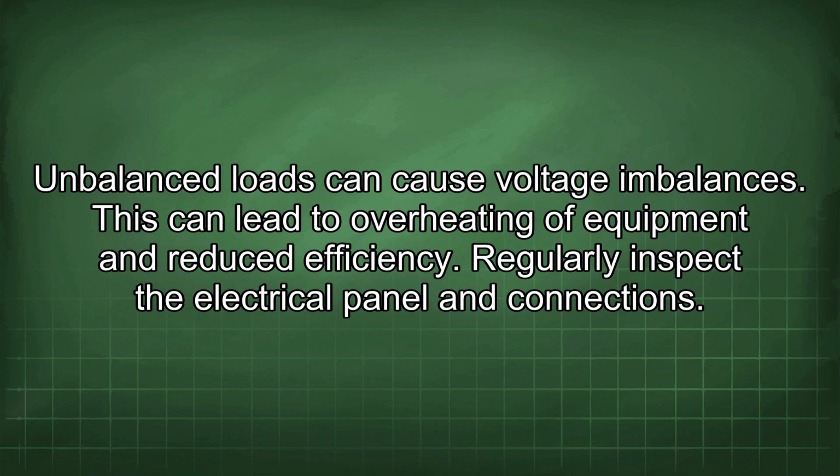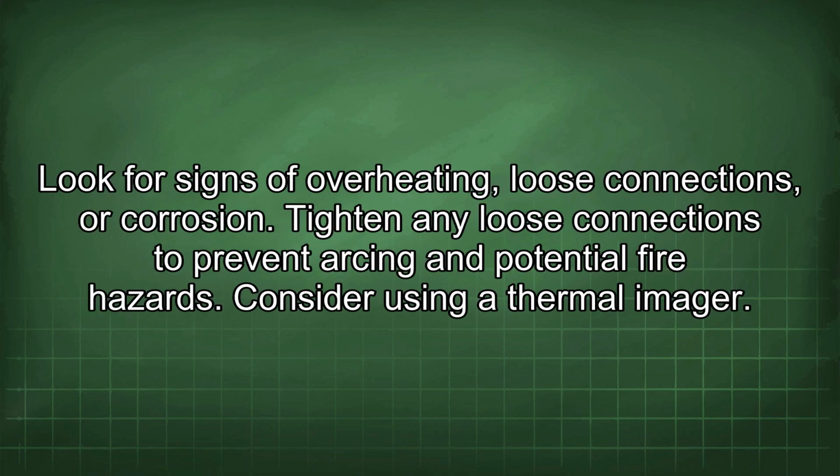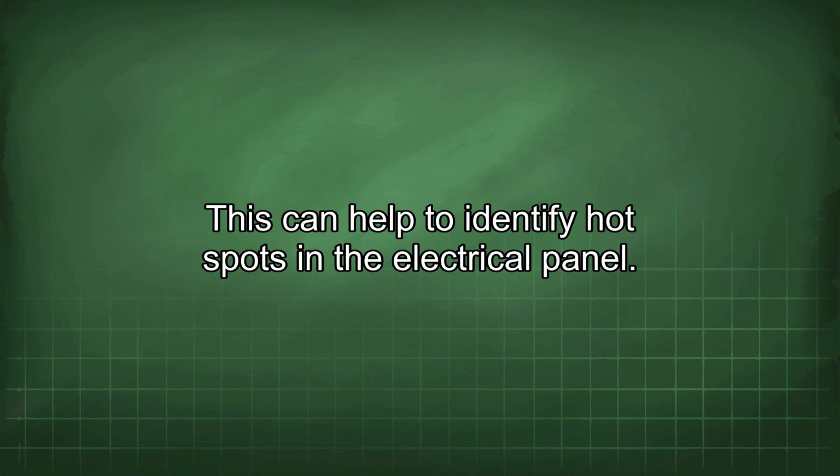Regularly inspect the electrical panel and connections. Look for signs of overheating, loose connections, or corrosion. Tighten any loose connections to prevent arcing and potential fire hazards. Consider using a thermal imager. This can help to identify hot spots in the electrical panel.